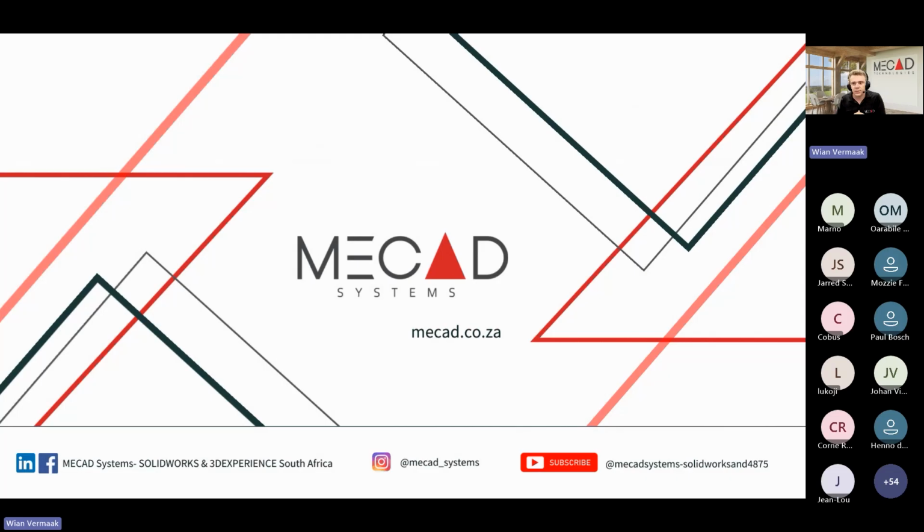Johan's asking, what settings are you changing for optimization? Only image quality, or is there more settings, and does this change for different or more complex parts? So the settings that it changes is only image quality at this stage, because we found this has the biggest effect. Remember, it opens the file up, and then it changes it on a document level. So only that part is going to have its image quality lowered, and the rest of the settings we found is negligible.